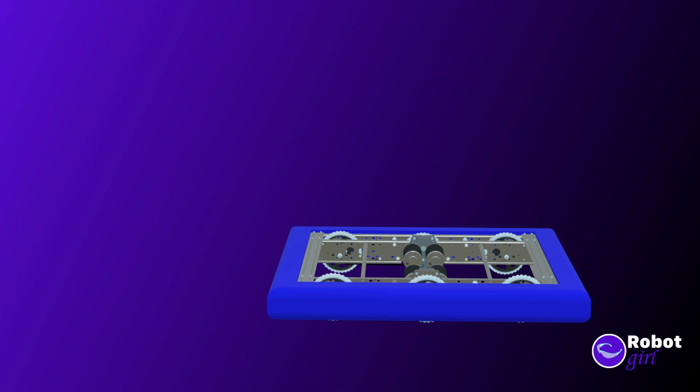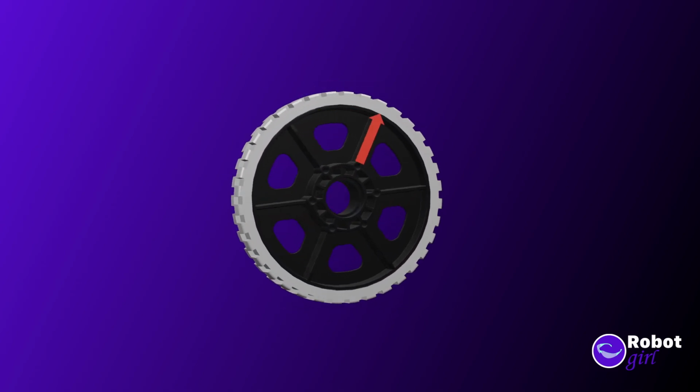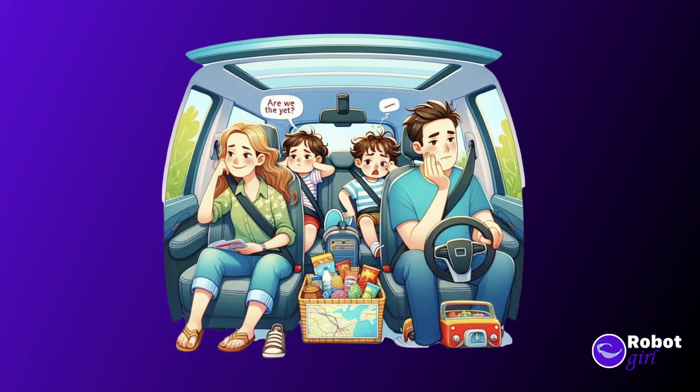The most common way that we can know how far the robot has driven is to use a motor encoder. I won't go too deep into how an encoder works because that's a topic for a different video, but the short explanation is that an encoder counts how many times the wheel goes around, and we can use the circumference of the wheel to know how far it traveled. The distance our robot has traveled is our measurement. As the robot is running, the code checks these values over and over in a loop. Imagine a bunch of kids in the back seat yelling, "Are we there yet?"